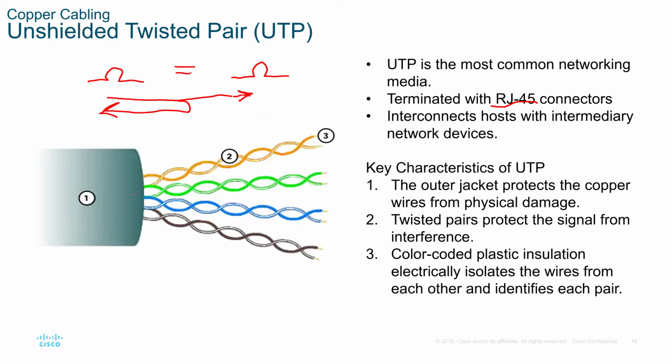If I took a cable that is connected to nothing and I put it into a handheld device, referred to as a time domain reflectometer, if it goes to nothing, the resistance goes from whatever the resistance of the wire is to an infinite resistance, so that the entire signal gets reflected back.